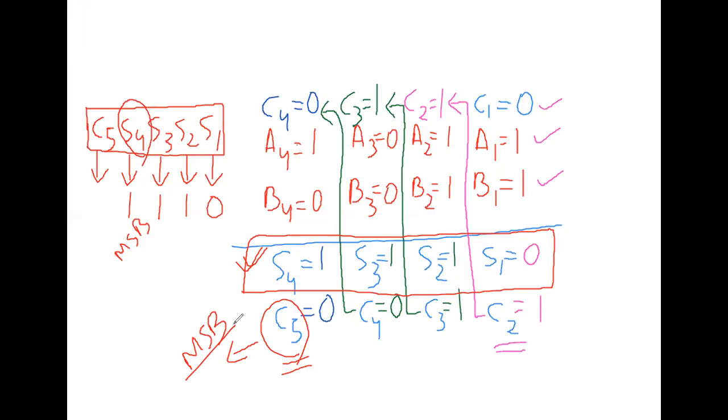Right, next we'll design the binary adder. Already I told you a binary adder is nothing but addition of two binary numbers, and we cannot use a half adder for design. Why? Because there is no option for the carry addition, right? That's why we have to take the full adder to design the binary adder. Okay, so let's go for the design process. This is how we can go for this process, right?